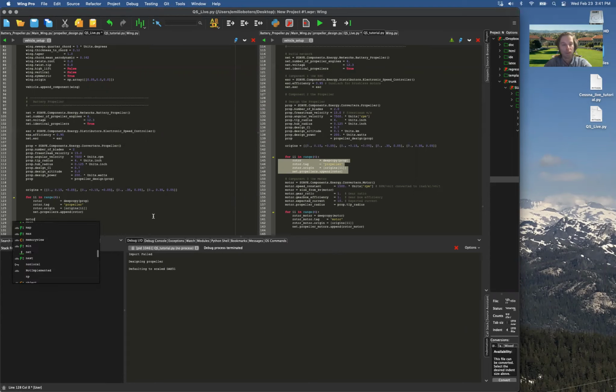Next, we'll do the motors. This will be another question mark. I didn't know the specifications of the motors, so we're going to size these out. And then we're going to assume a speed constant. This is something that I was able to get fairly close to, I think. So it's a 1500 RPM per volt speed constant.